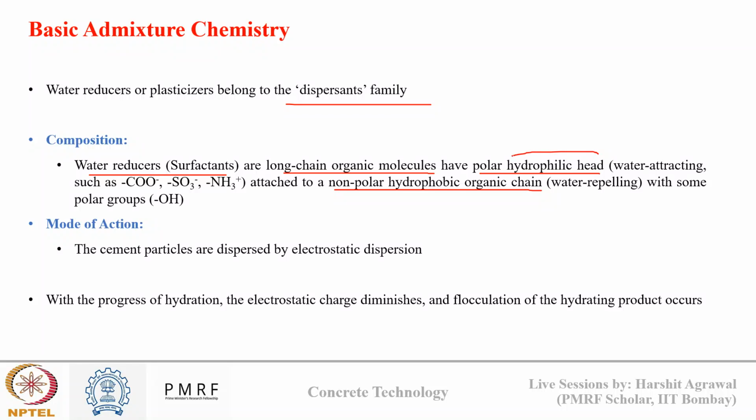The hydrophilic head present in these plasticizers is water attracting. What are these hydrophilic heads? These are the acid group, the sulfonate group, or the amine group. They are attached to a long chain of non-polar hydrocarbon, the hydrophobic chain. So this is a hydrocarbon chain which is non-polar and water repelling. The combination of these two elements in a plasticizer makes them act as a dispersant.